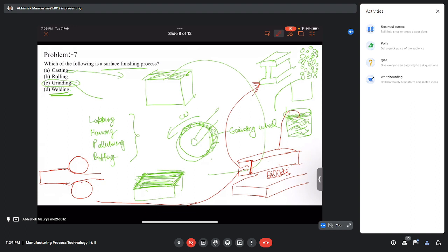So earlier the billet was like this, and now what I did, I tried to pass this billet through the gaps of the roller. Meanwhile, I apply some compressive forces. And what is unique about this? The contour shape of this roller, it was something like I set. Okay.